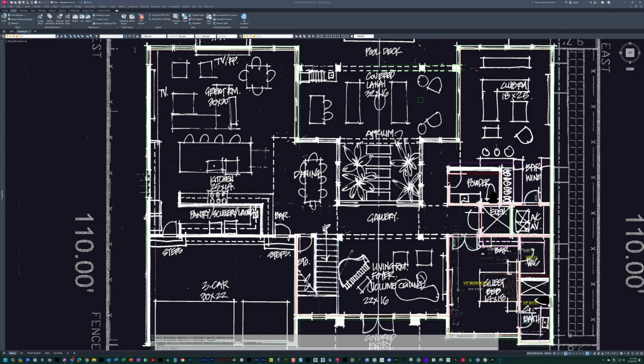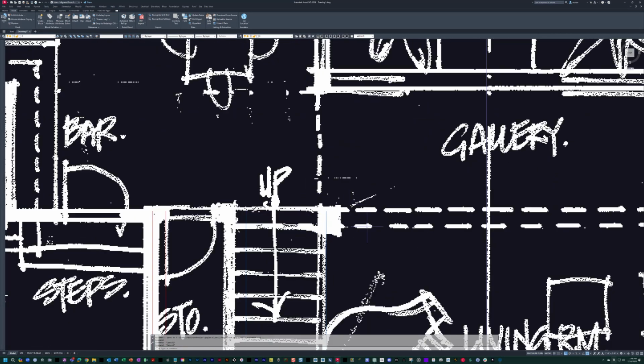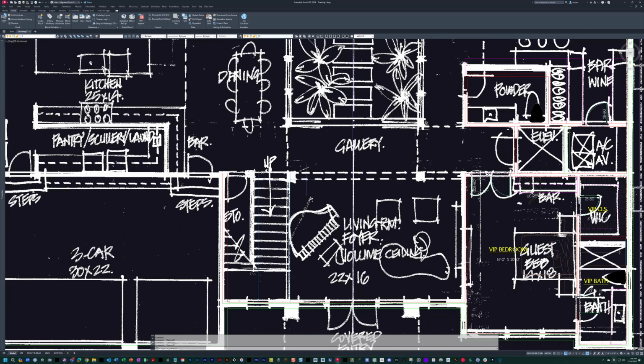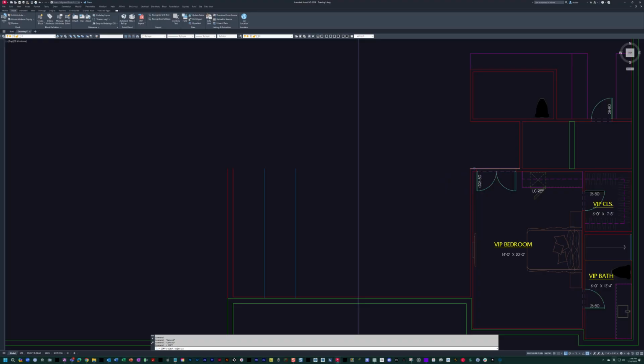Where we want to, this is getting back into maybe a design standpoint, but where this goes is going to be related to this corner, which is related to this corner, which will be related to this stair. So everything is going to kind of come off of this corner right here. So diving into here, I know this is going to be a corner. We want to look at the stair, so I'm going to turn our image off. It's going to come from here. That's going to be our wall. And in fact, I can even offset this 4 inches.